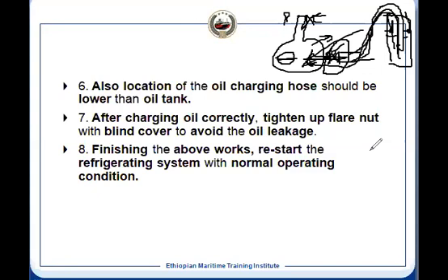So to avoid that, lube oil is the first thing. Lube oil should be there sufficiently. Pressure should be there sufficiently, so that even if the system does not perform for some other reason, it will not be damaged. So that is most important. That's why lube oil is very, very critical. So we cannot run the compressor with a low lube oil level. Is it clear? Understood, Dev?